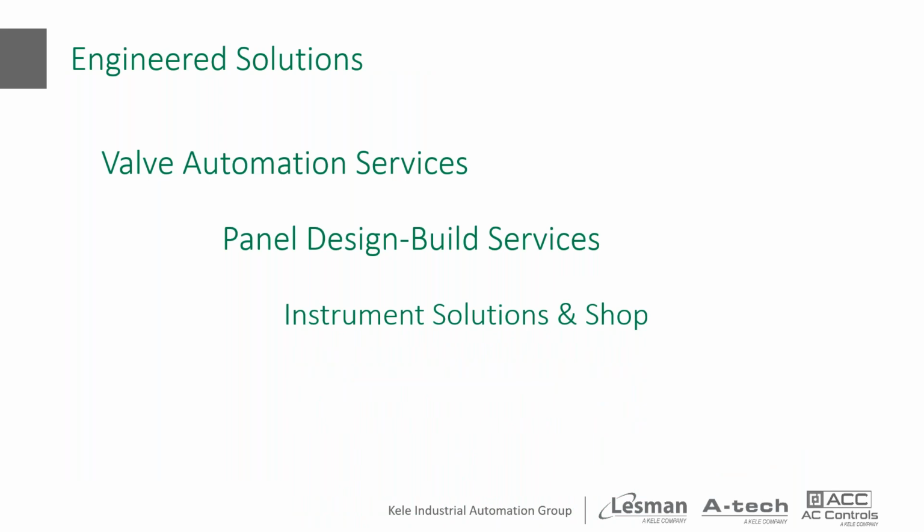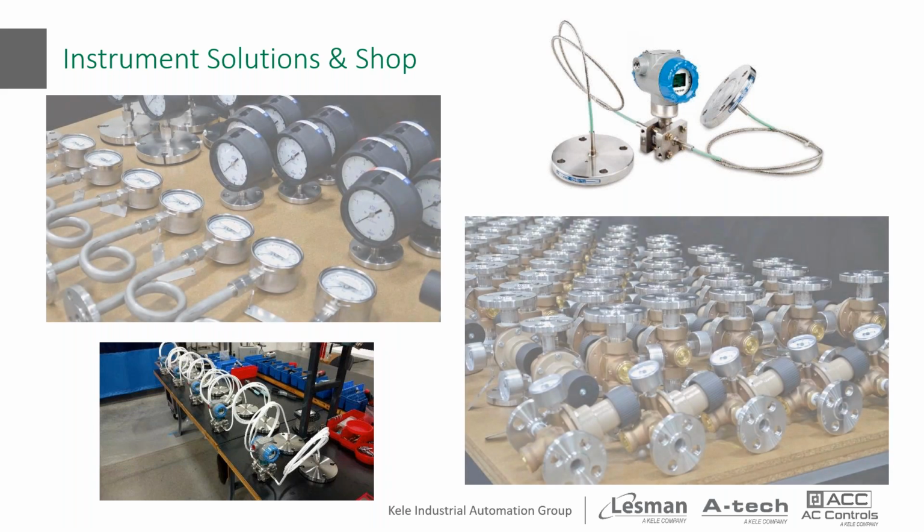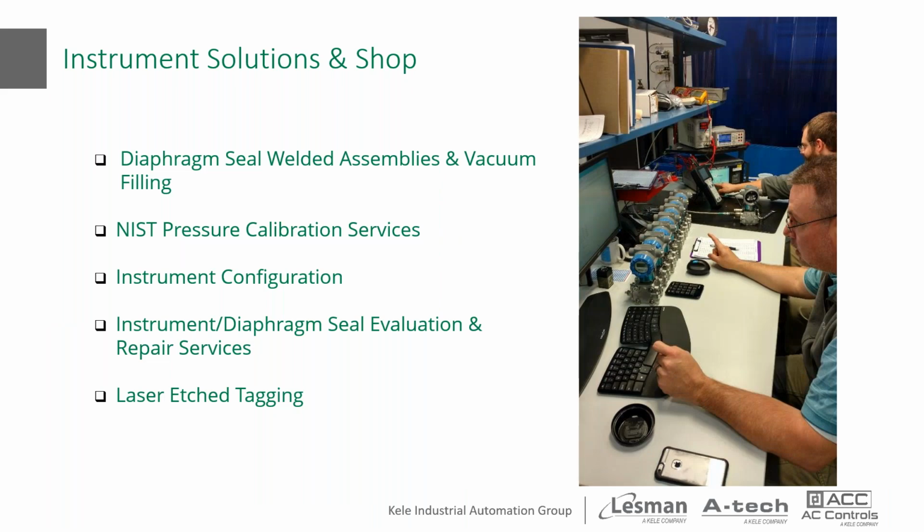You've already seen a large part of how our instrument solutions and shop services can help you with regard to diaphragm seal instruments. We can also provide any number of prefabricated instruments like the ones you see here, where the instruments simply needed an ANSI flange added to it and a laser etch tag. The instrument shop is where we perform diaphragm seal welding and vacuum filling for instrument assemblies. All pressure devices are calibrated to NIST standards. We highly recommend that you allow us to pre-configure your instrument so that will allow you to have a ready to install device when it hits the dock.